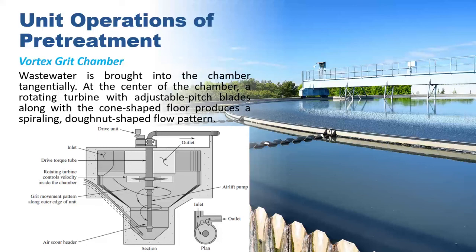This results in a lower exit velocity than the influent velocity and thus prevents grit from being drawn into the effluent flow. It should be noted that centrifugal acceleration does not play a significant role in removing the particles. The velocities are too low.